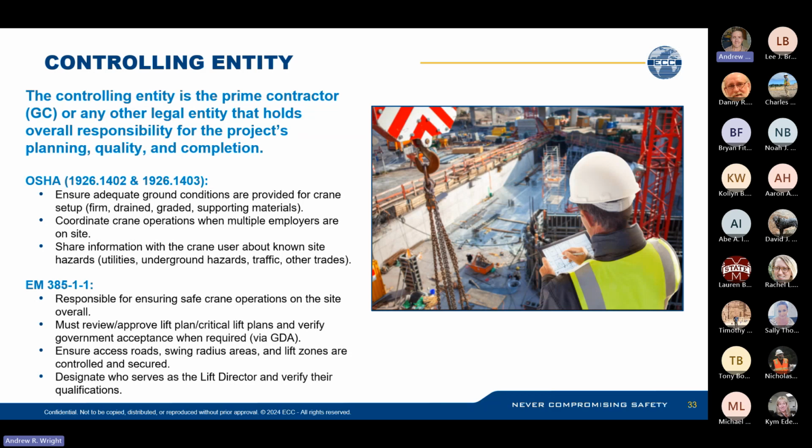And you could always look at the building exterior if you're near one for evidence of anything underground. You could look for gas service lines or water service lines, and you could also have the area located, if you want to be extra cautious, to find anything that is a subsurface anomaly.